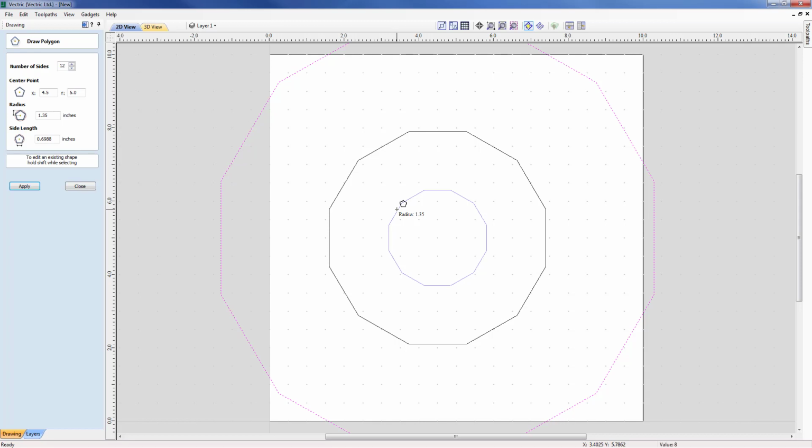So I can do 8s and then specify the radius as 4d, and you can see that we've got a 8-sided polygon with its diameter 4. So that shows the different options for specifying a polygon. We can either specify the radius or diameter based upon the current number of sides, or add into the equation the number of sides and then the diameter or radius following that.